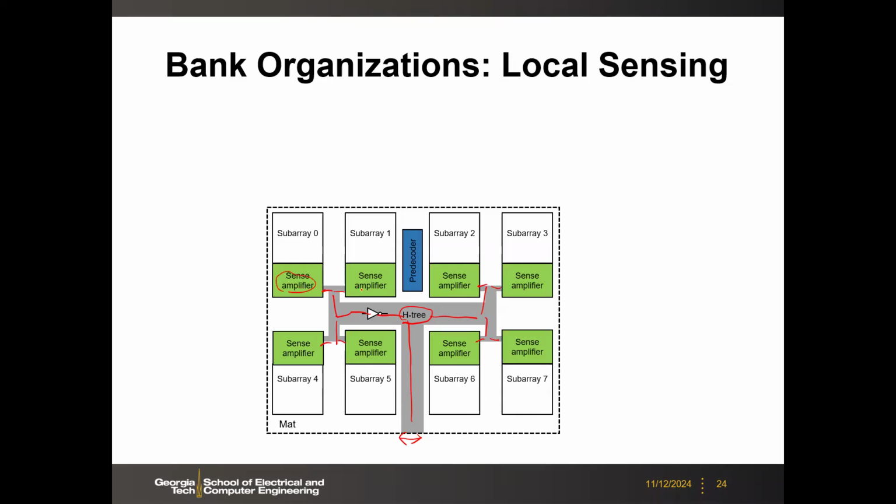You are going to sense the data at each subarray, and then you digitize the output, and then aggregate the bits, right? Of course, depending on the architecture design, you may only need to activate one subarray or two subarrays, and the others are idle. You only fetch the data from those two, if that number of bits can satisfy your bandwidth from your I/O.